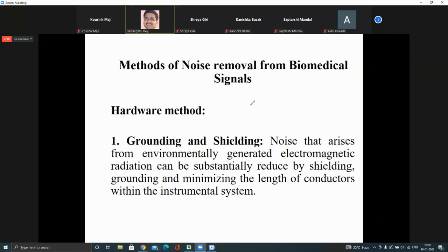Okay. And shielding, say this is a wire and the wire is having some resistance. So shielding means you are covering the wire using a metal portion. This metal portion is not connected to the wire, it is insulated from the wire, but it is like this. And usually the shield is grounded. Probably you have heard the term shielding, at least in your AC bridge.